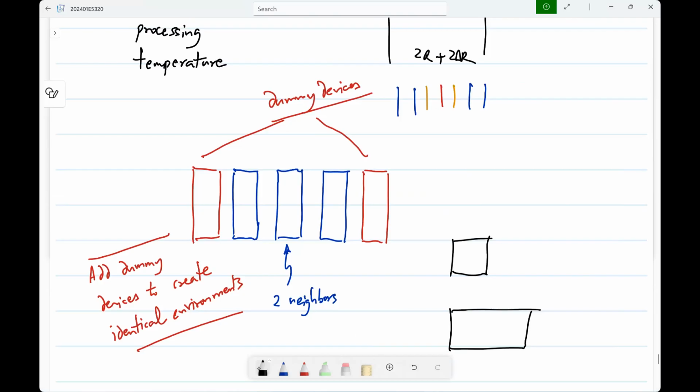By the way, the components can vary very widely in value, right? Like for instance, you have heard of digital to analog and analog to digital converters in some basic form. In many such circuits, if you have a 10-bit digital to analog converter, there will be some element, it could be a capacitor, resistor, or MOS transistor, which has a weight of 2 to the 9, and then some element which has a weight of 1.